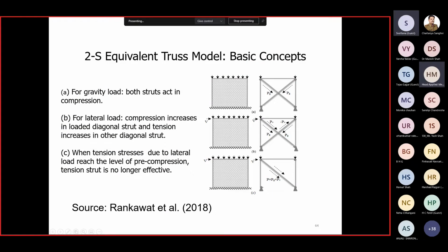So now here is a bit of complexity that comes with this model, how it was understood. First, if you have gravity loading without seismic, then each of these vertical struts will work, and they will take a portion of this that is assumed. They take gravity loading, and there is no gravity loading in the tie columns, but just in these struts.